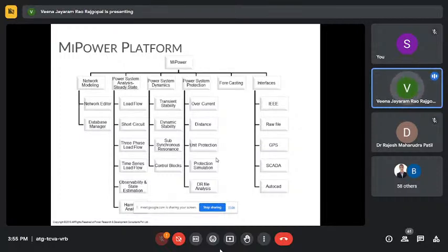Say, for example, if I'm doing magnetizing inrush current studies, that will be my problem statement. My solution will be to do an electromagnetic transient analysis, because I cannot do a line charging or transformer charging study using transient stability. If we see any of the software packages or any analysis, most of the studies we do will be in the RMS domain. We'll be using RMS values while doing the analysis, except for electromagnetic transient, where all the values are instantaneous values.